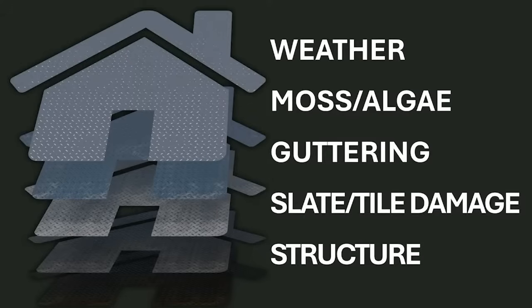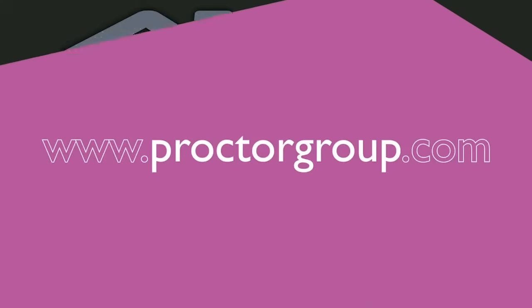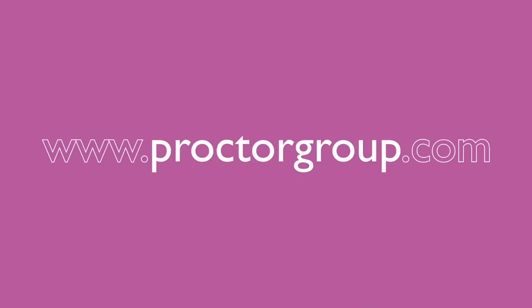To address these issues and ensure the longevity of the roof system, it's essential to schedule regular inspections and maintenance by qualified roofing professionals. This includes cleaning gutters, removing moss and debris, repairing damaged shingles or tiles, and addressing any structural or flashing issues as needed. Additionally, investing in high-quality roofing materials and ensuring proper installation can help minimise maintenance requirements and prolong the life of the roof. That concludes today's presentation, and we'll now move on to the Q&A session.